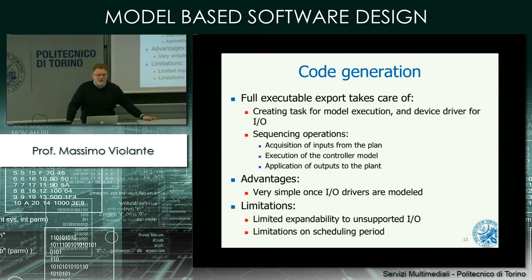So basically, once you instantiated your IOs on the Simulink schematic, once you developed your own controller logic based on Stateflow or based on a sequence of charts that are interconnected, you can export the whole binary. This means that the platform support package, when you ask to deploy your model to hardware, takes care of creating the scheduling of the task resulting from your model, takes care of generating the device drivers corresponding to the different IOs that you are using.